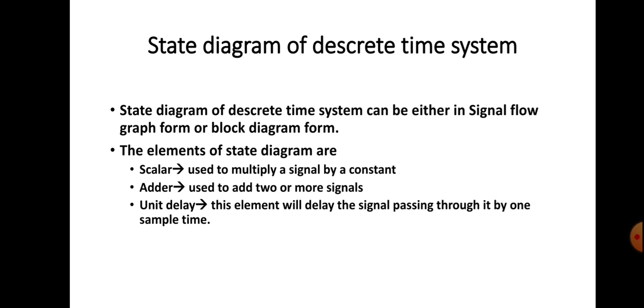The basic elements in both these cases, block diagram and signal flow graph, the basic elements of the state diagram, are scalar, adder and unit delay. In the case of continuous time systems, it was scalar, adder and integrator. That was the basic elements.